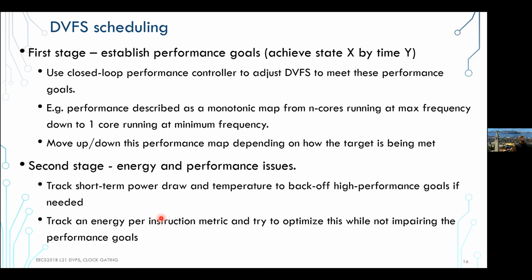So if you have a high performing task, it actually pays off more to throw it at a really good core, which can finish in a reasonable amount of time, than run it for a very long time on this low power core and overlap kind of a lot of operations. It's not energy efficient because you're fetching the data, bringing it somewhere back, etc. Plus it annoys the user, right? And so there are these balancing acts that the OS needs to basically decide, right?